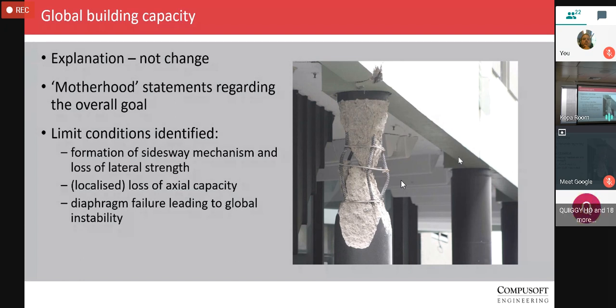So those are probably not clauses that you're going to be referencing and using for design calculations day in, day out, and it's a shame they're at the back, but they should be read by everyone, I think, just to keep in mind what it is that is the driver for assessments. Certainly we still see too many around the place where the idea that it's a displacement-based framework looking for sway and so forth gets lost, and it just defaults back to a force-based demand-to-capacity ratio, which fairly obviously leads to pretty poor results.